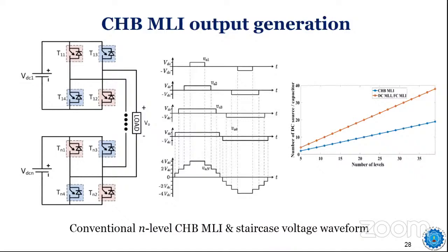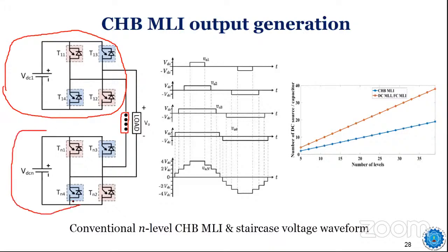This is the basic concept of a multi-level inverter, where you can see that you integrate H-bridges like this. It shows a number of H-bridges being integrated. Let's suppose four H-bridges are connected. If you connect four such bridges, what will happen? You need four different sources, right? And the logic for operating these switches is very simple.